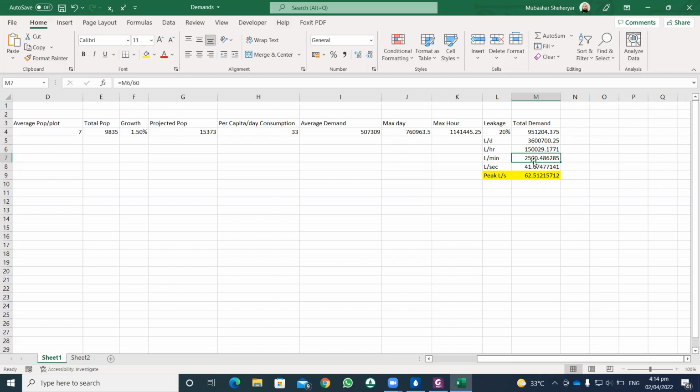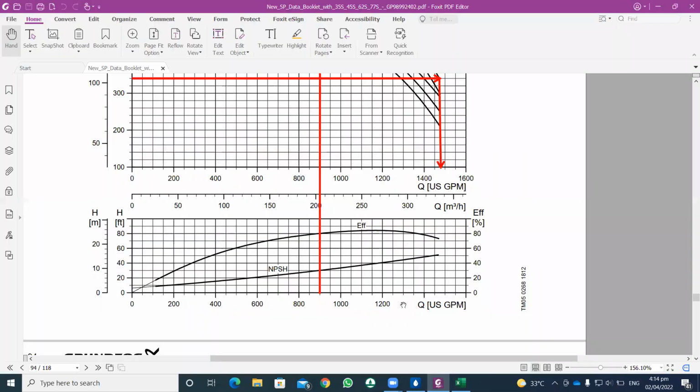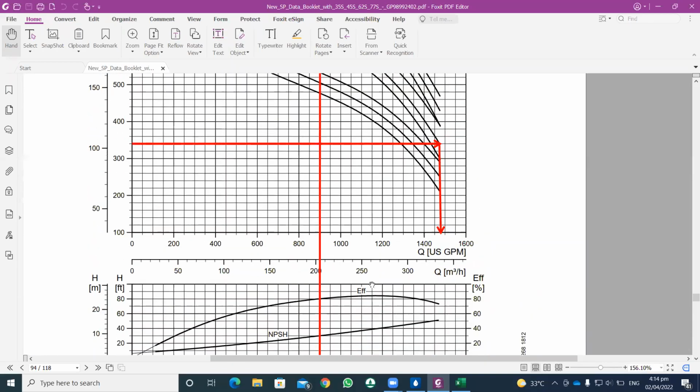So I just took a value of about 3000 liters per minute for a factor of safety, and then converted it into gallons per minute. You can easily convert that using different conversion tools. For example, the capacity of a system is about 840 gallons per minute.